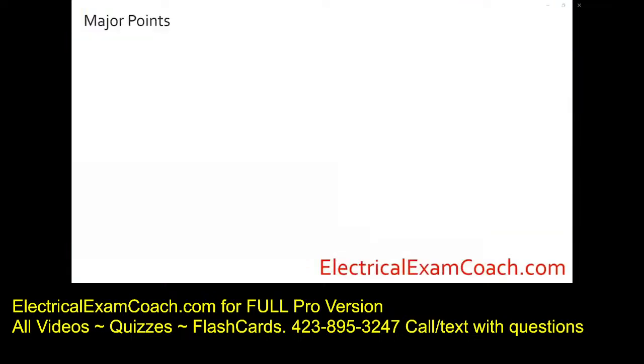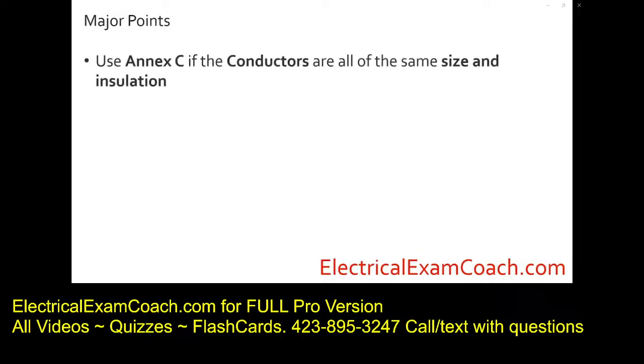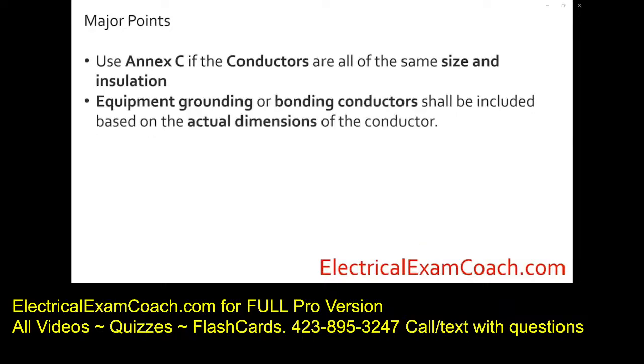Before we jump into the practice questions, let's go ahead and hit the major points. We're going to use Annex C when all of the conductors are of the same size and insulation. Equipment grounding and bonding conductors shall be included based off the actual dimensions of the conductor. It's not like we did in box fill. If there is a grounding conductor in that pipe, it counts 1 for 1, and all of them count. If you've got 10 of them, they all count.